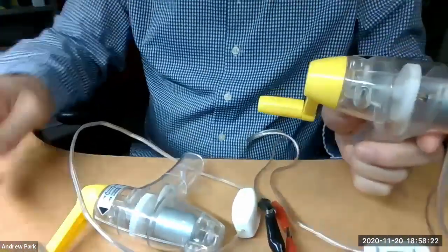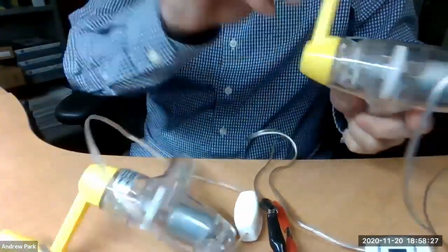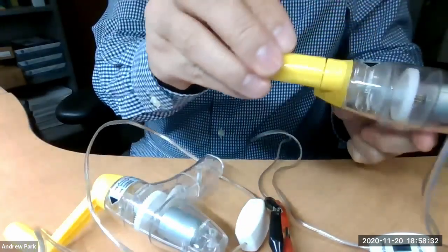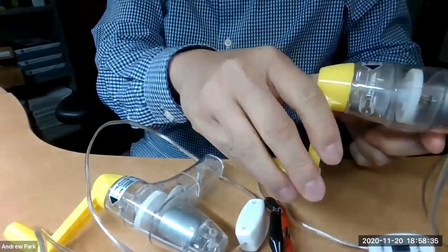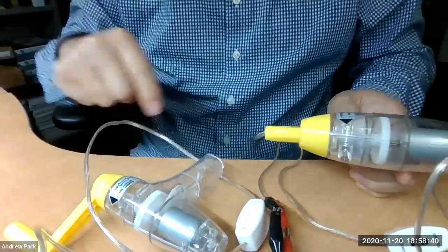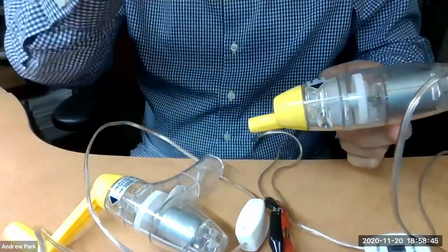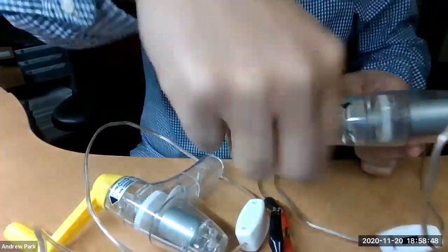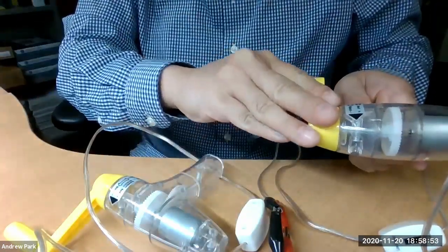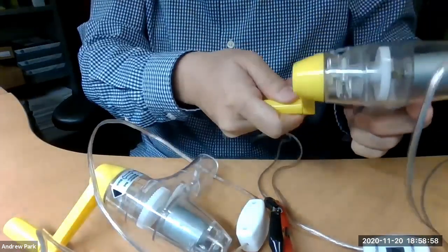By the way, you can see that these two are not connected one-to-one. When I turn this fast, you see it turning, but watch when I turn this very slowly. When I turn this very slowly, making sure I'm not generating so much current, it's not a one-to-one relationship. It's a mechanical energy to current to mechanical thing, and there are enough losses there that if I do this slowly enough, I can turn this without that other thing turning. But if I do it fast, then it turns.